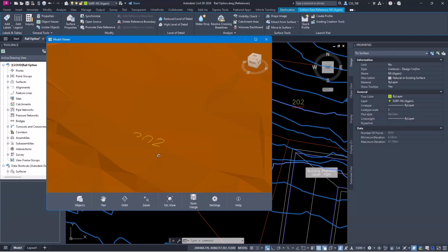There's another thought that colleagues had where you could use one of the Express tools to explode the text out to being just line work, convert it to 3D polylines, and drape it on the surface. Another way you could potentially approach it, but this one might be useful. So hopefully that gives some people some ideas on what to do. Anyway, thank you, Jonathan. No, thank you.